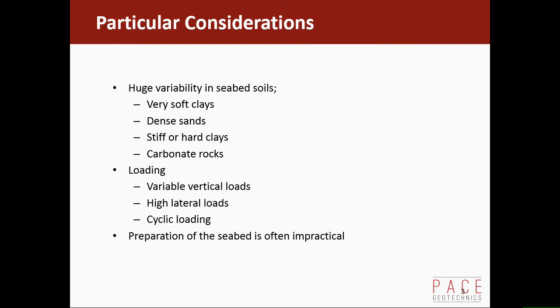One of the things I enjoy about offshore foundation design is if you're working onshore, you design a building like this, it's basically a vertical load. You've got no real horizontal load on any structure. Maybe on bridges you might have to consider horizontal loading and so on. With subsea structures, there's always a big component of horizontal loading, and sometimes, in fact often, that is the driving load case, and you've got to work out how you're going to achieve that lateral resistance combined with your vertical capacity.